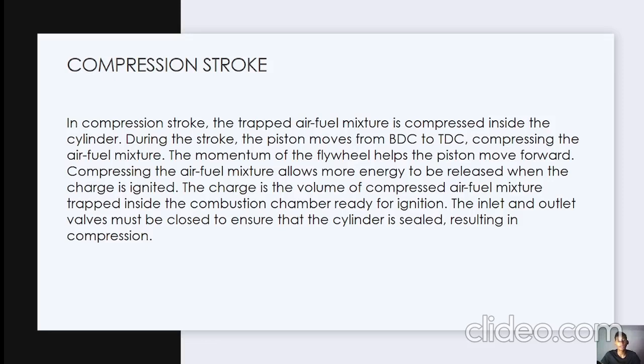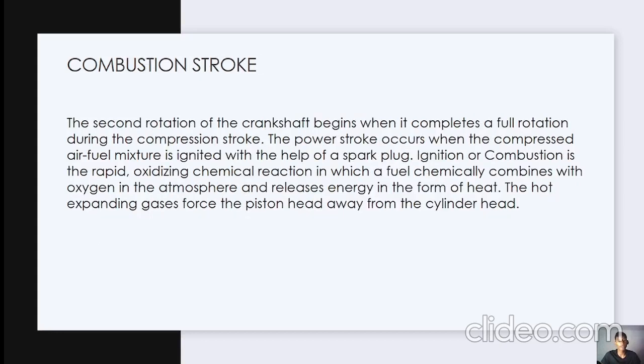The inlet and outlet valves must be closed to ensure that the cylinder is sealed, resulting in compression. The next stroke is the combustion stroke. The second rotation of the crankshaft begins when it completes a full rotation during the compression stroke.